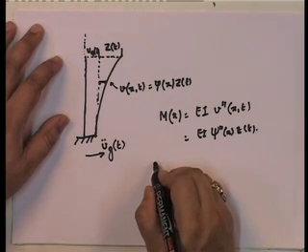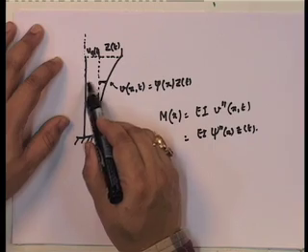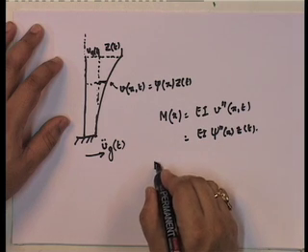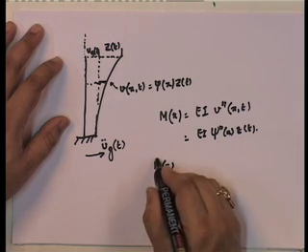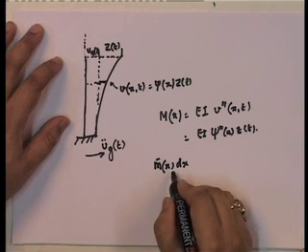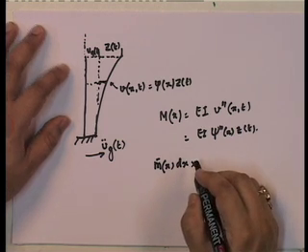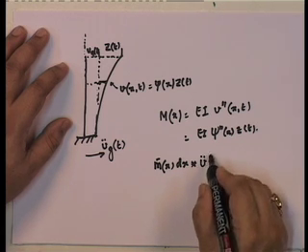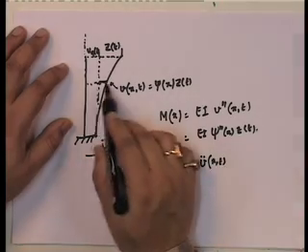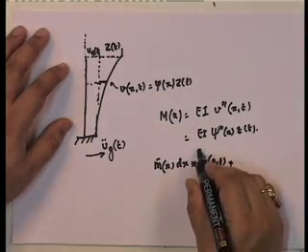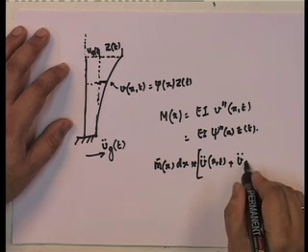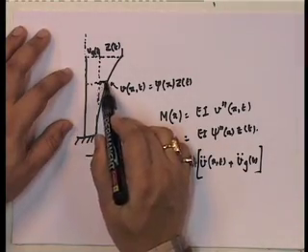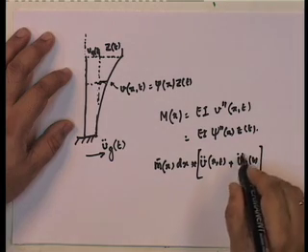Let us look at what is the acceleration that this point undergoes. The acceleration that this point undergoes is the following. It is equal to m bar x dx, that is again the mass, times the acceleration, and the acceleration is equal to v double dot x of t, that is this part, plus v g double dot, because that is the acceleration. The mass was here and it's here, so it is being subjected to that acceleration.